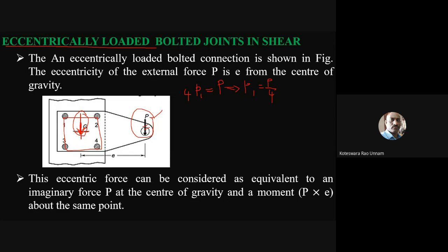But here the problem is the load is not acting at the center of gravity. It has some offset distance here. So we cannot do that. What we need to do is find out the effect of this force acting at this location. To find that, we need to transfer this force from this location to the center of gravity G.